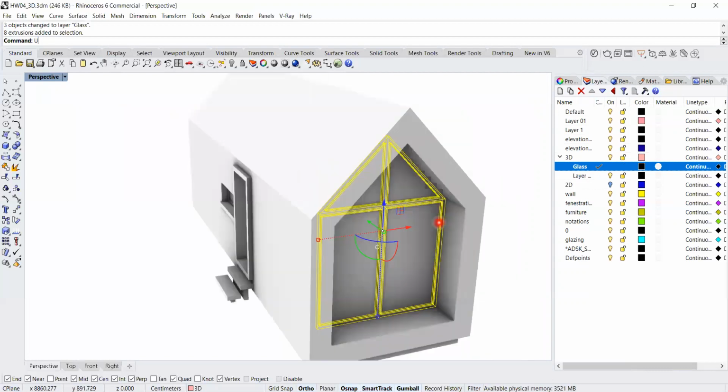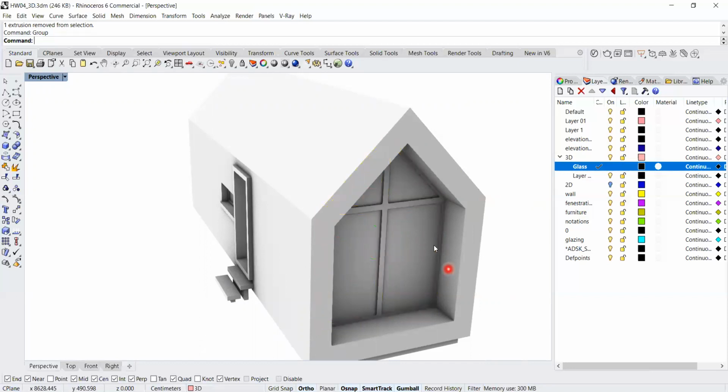So I just ungroup it. Pressing Control, I deselect inside glass parts, and then group it again. So the frames will be grouped again if I select them, but the glass parts are not anymore. So you can select all these glasses and, by pressing Control G or writing group, make it a group,